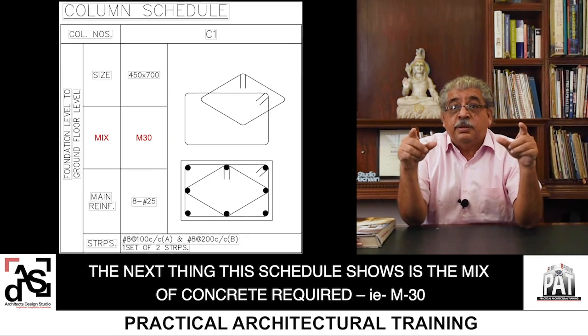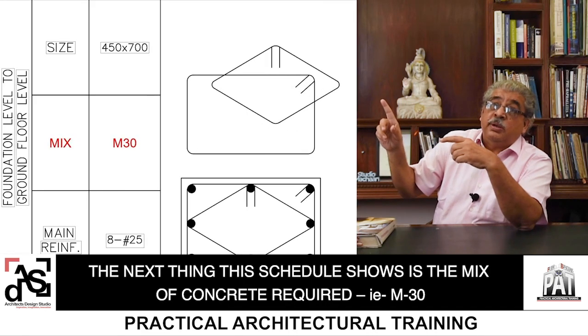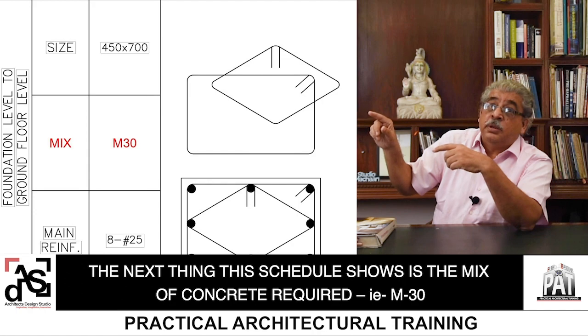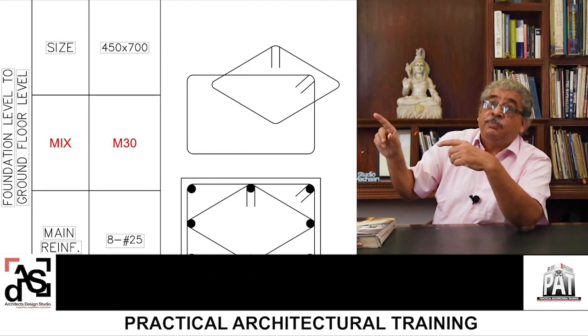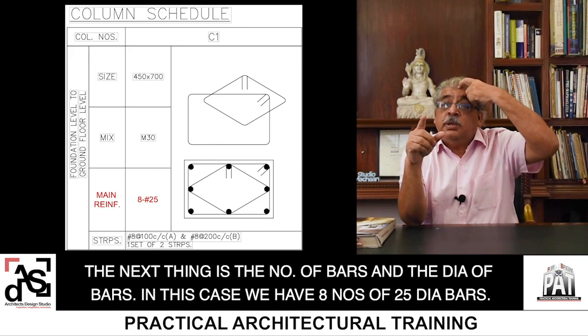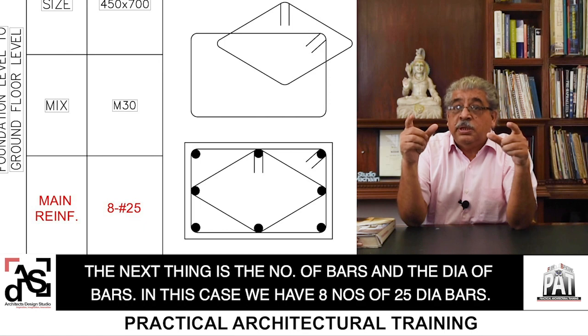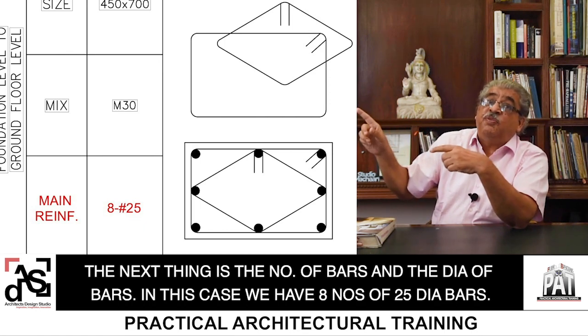The next thing this schedule shows is the mix of concrete required. Again, have a closer look at M30. So M30 is the mix of concrete required. The next thing is the number of bars and the dia of the bars. In this case, we have 8 numbers of 25 dia bars.